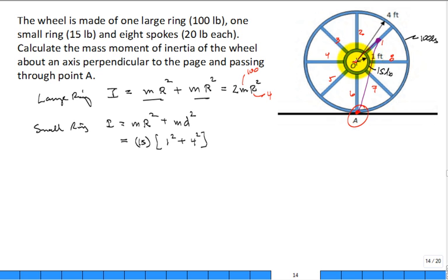If you do it that way, you're going to get a triangle, and you probably want to use this angle right here, which is fairly easy to get. For rod 8, that triangle is a right triangle. I like that. It's 90 degrees. But for rod 1, it's not 90 degrees for that angle, and we're going to use the law of cosines. It's a good little review. You could do it that way. And you'll have to do the same thing for rod 7, like that.